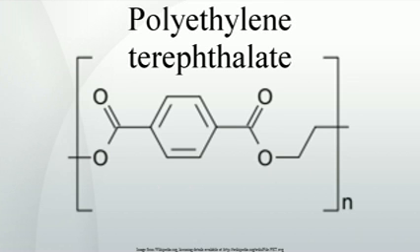One way to alleviate this is to use a copolymer. Comonomers such as CHDM or isophthalic acid lower the melting temperature and reduce the degree of crystallinity of PET, especially important when the material is used for bottle manufacturing. Thus, the resin can be plastically formed at lower temperatures and/or with lower force. This helps to prevent degradation, reducing the acetaldehyde content of the finished product to an acceptable, that is, unnoticeable, level. See copolymers, above.